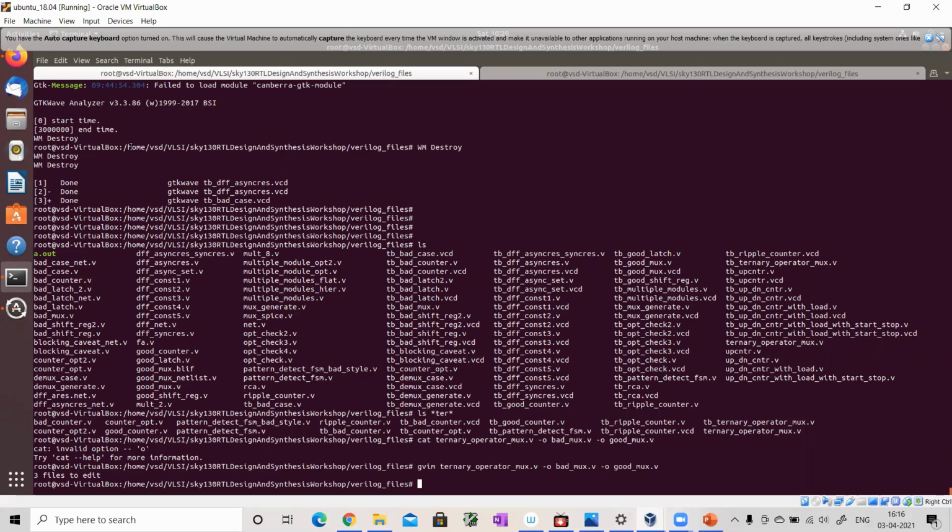Quickly, if we recap, in the last session we saw that to run GLS we need the netlist, the Verilog models of the standard cell libraries, and then we need the test bench. We submit all these three to iVerilog, and iVerilog dumps out the VCD file, and the VCD file contains the waveform which will be viewed using the GTKWave tool. Clear? So we have some files here. We will quickly have a look at them. These are the files we are going to use for this lab.